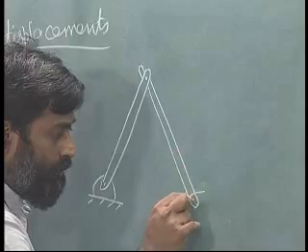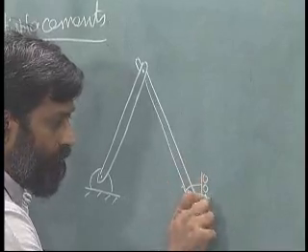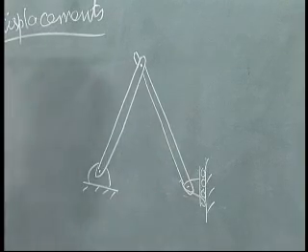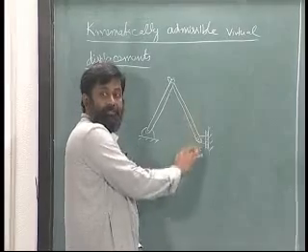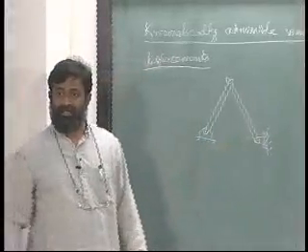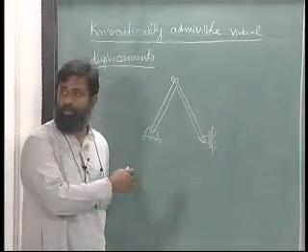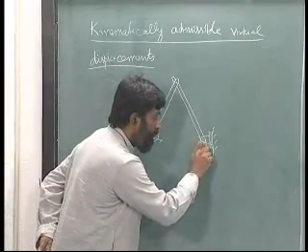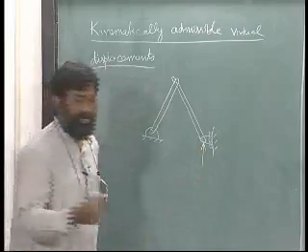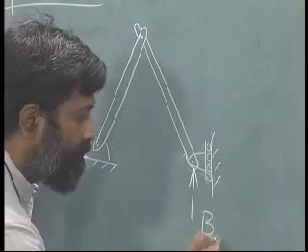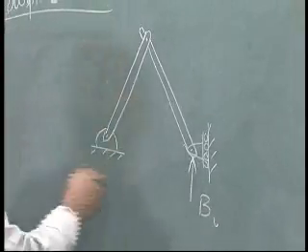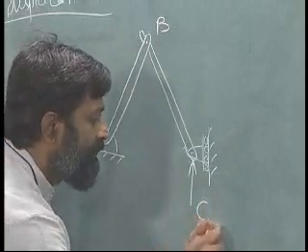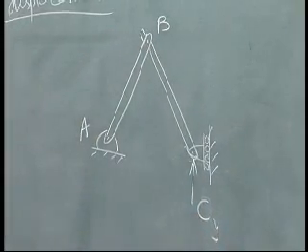So, I am just going to substitute with releasing only the vertical displacement, and I apply a virtual displacement here to look at the equilibrium. Of course, when I release, mind you, I have to apply the appropriate unknown reaction. In this particular case, let us say this is B, I am sorry, I think A, B, C was what was used. So, this should be C along the y direction, all right.